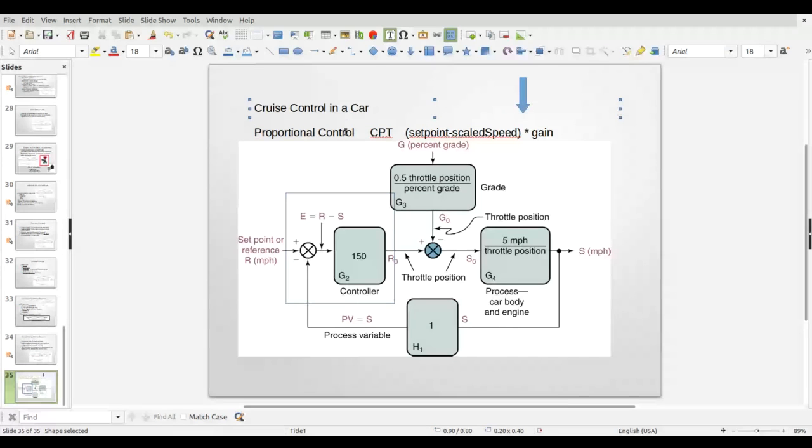This proportional control is so trivially easy to do, and it does a pretty nice job. If you wanted to do it really easy, you could just set the gain to 1, and so basically it's not even there. You just take your error and feed it through, and then you have to, of course, scale it back out. It's just very, very easy to do proportional control. So I will cover that, and the first thing we're going to do next week is some proportional control.